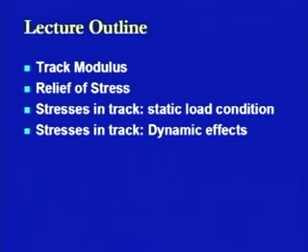Now, when we take up the stresses, we are talking about the different loads which are coming from different quarters. Some of these loads we have already discussed previously when we discussed the resistances, or the coning of wheels, because of which different loads are coming from the longitudinal direction, the lateral direction, the vertical direction or the horizontal direction and likewise. On the basis of all those resistances or loads which have been offered on a track, we will today be discussing the stresses.